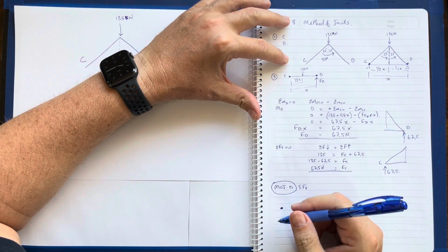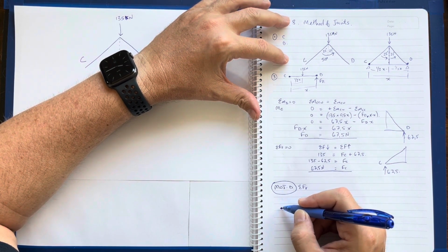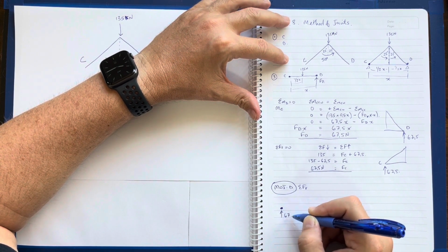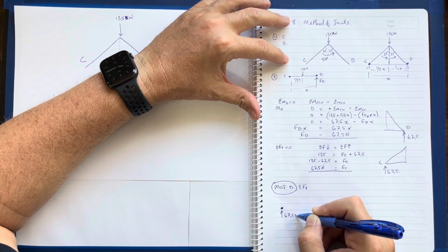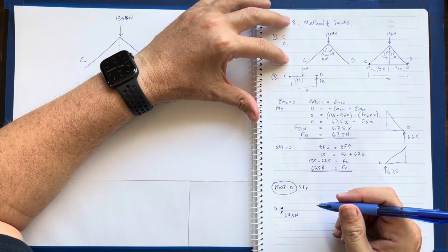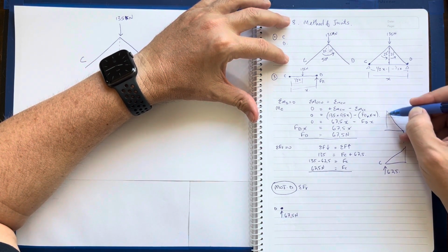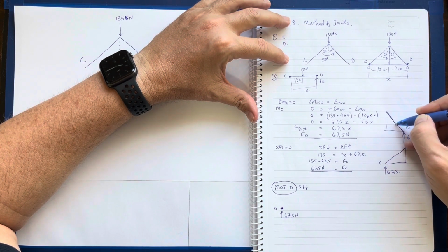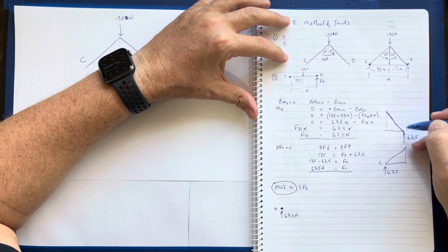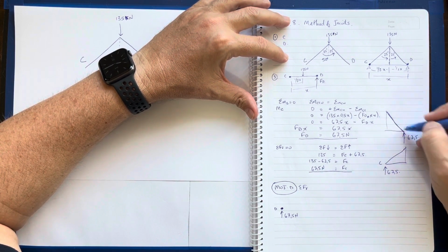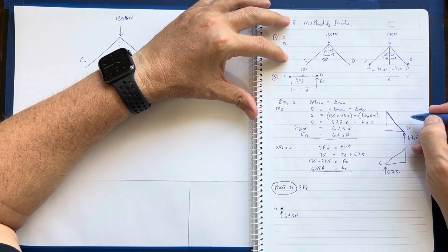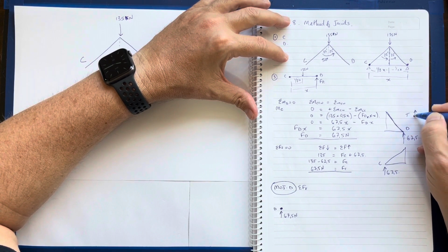I look at the joint and I see that externally I have a force of 67.5 newtons pushing upwards, which is into that joint D. But I'm actually trying to solve the force in this member here, and I don't know what it is. So automatically in method of joints, I assume that member D is in tension. If it's in tension, it's moving away from the joint.